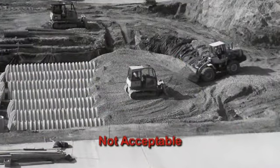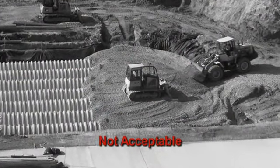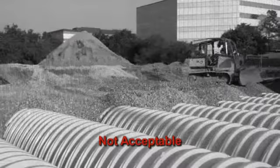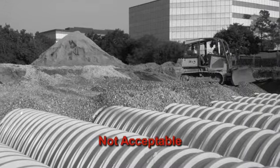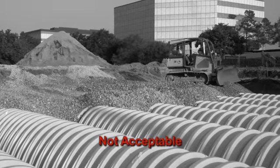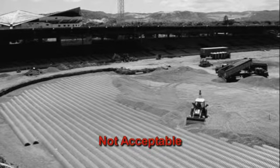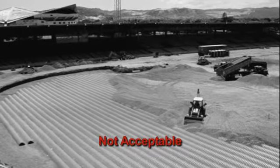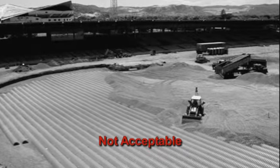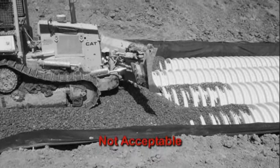The dump and push method is the placement of embedment stone around and above chambers by pushing stone with construction equipment, such as dozers or loaders, prior to the stone being placed between chamber rows, perimeters, and over the top of the chambers. Dump and push is not an acceptable method to place embedment stone, and any damage to chambers resulting from the use of this method will not be covered by the standard ADS product warranty.